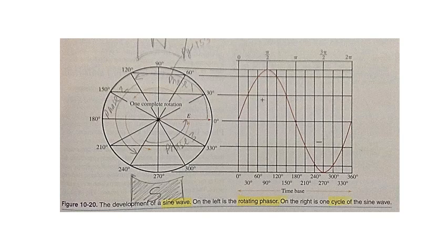The development of an AC wave is shown in figure 10-20. This wave is from a single coil armature, represented by the rotating vector making one revolution through a magnetic field. Assume that the peak induced voltage is 10 volts. Using a scale in which 1 inch equals 5 volts, the vector is 2 inches, or 10 volts long. Vectors of this nature are assumed to rotate in a counterclockwise direction.